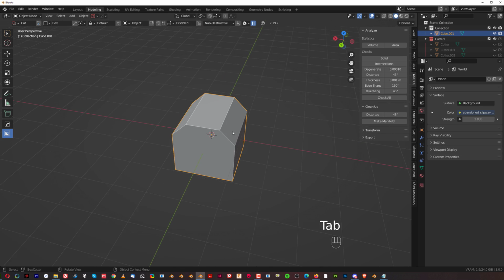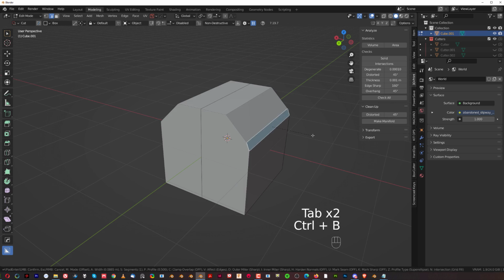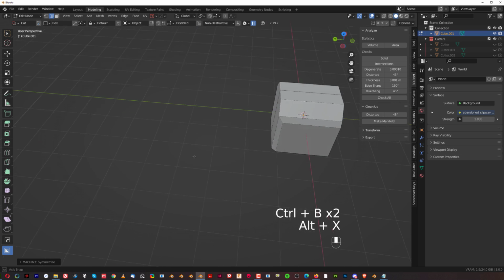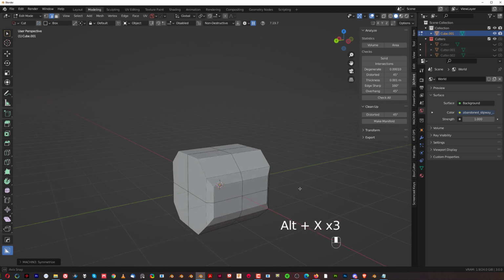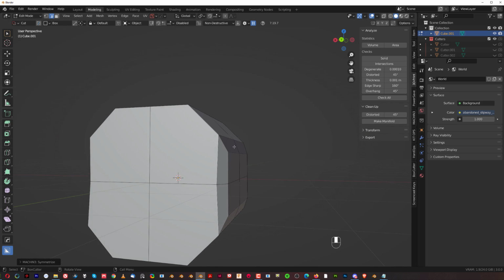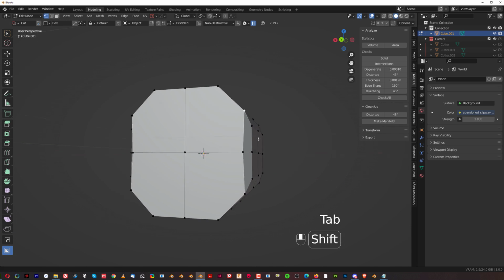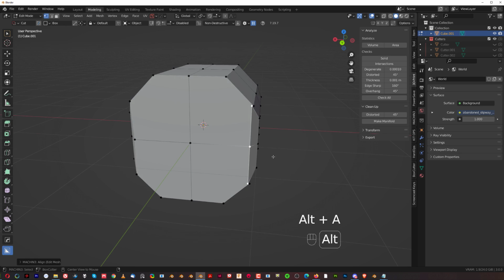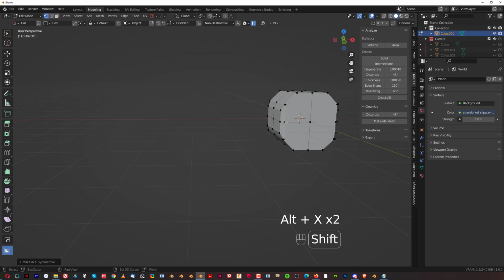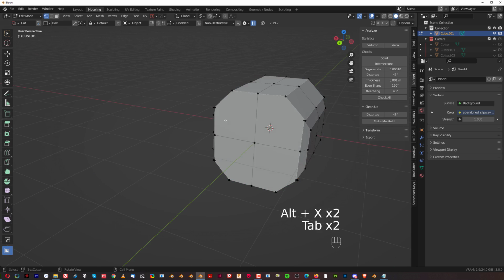So when you work with something and you create some kind of a really cool shape, and then you suddenly want to see how this looks mirrored, Alt X and you're done, Alt X and you're done. That's how fast this is, okay? See what I mean? And then let's say I wanted to straighten this out, I'm going to use Align. So I'm going to select these two verts, this one, Alt A, left, and then I'm going to symmetrize it here and symmetrize it here. See what I mean? How easy it is.